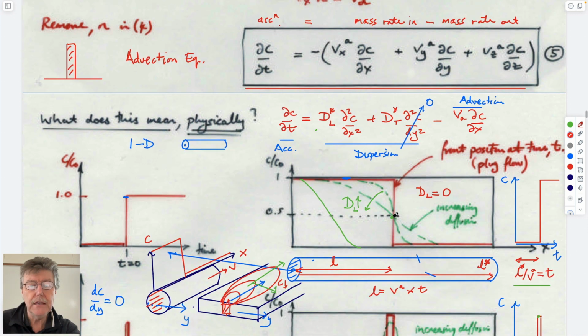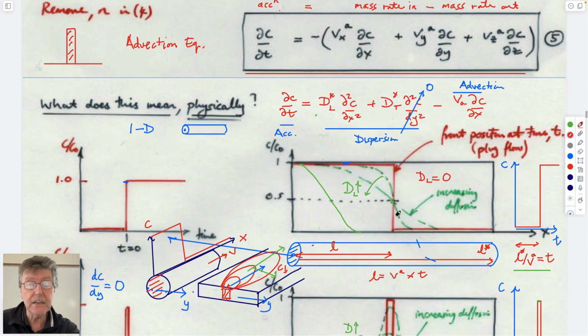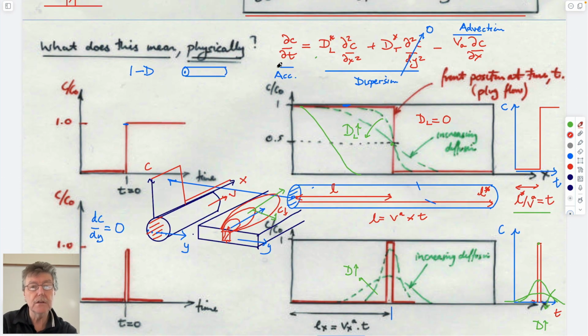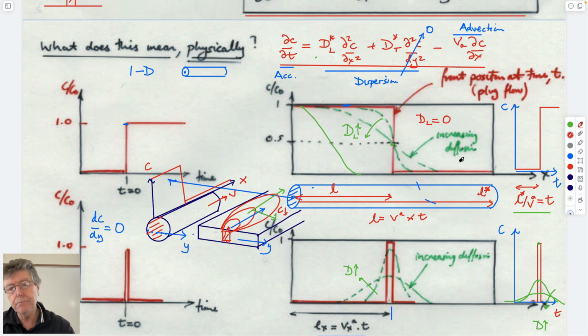We use the conservation equations for diffusion and advection to derive the advection-dispersion equation, which gives us these behaviors if we solve it, and which we will do today, or look at solutions for it. And we characterize the behavior in terms of an upstream boundary condition, flow through the porous medium, and then the residence time distribution curve at the outlet, defining exactly what happens to a receptor at the arrival.